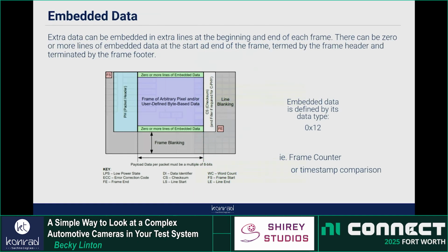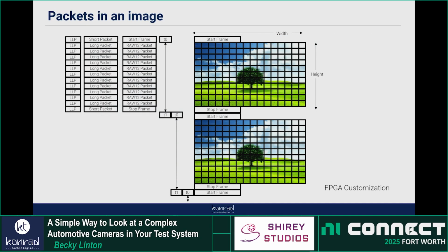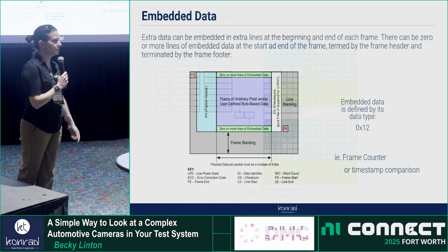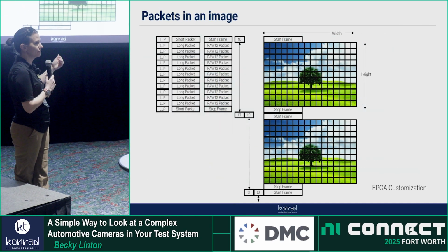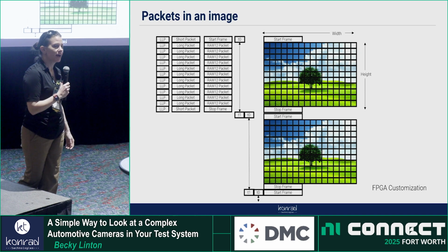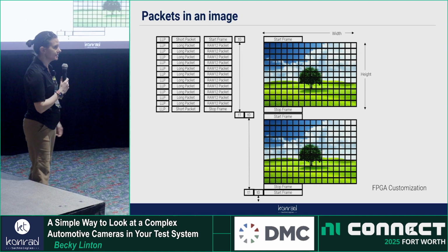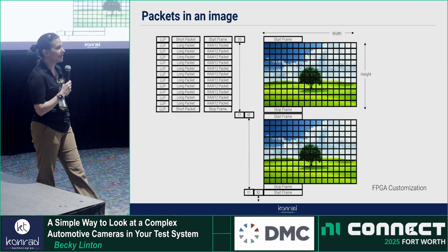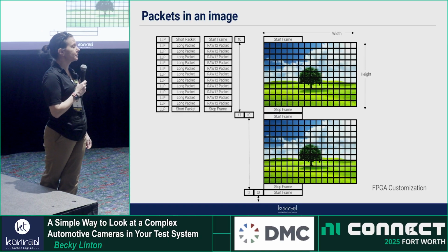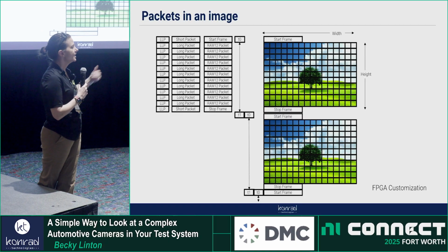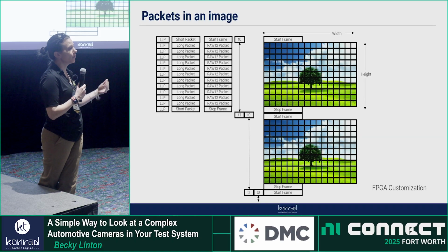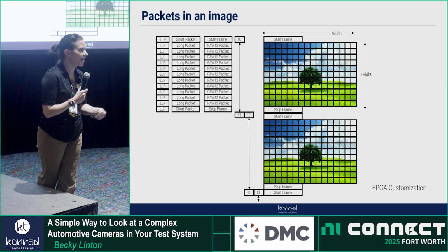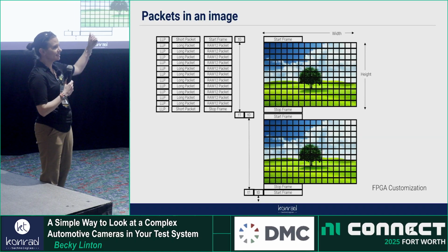That's a very good point Luis just brought up, the number of channels. Like he said, on the host, if you're just looking at 2 channels and calculating the frame rate, it's probably accurate. We have 24 cameras at a time that we are logging to disk and testing. They may or may not be enabled test sockets. So we have 3 of the 148X cards. The customer can put in GMSL or FPD Link. We have to auto detect whatever they've put in, and then they get to pick the camera type.